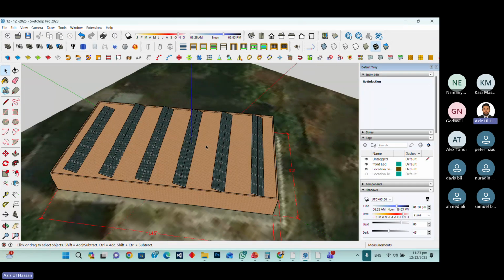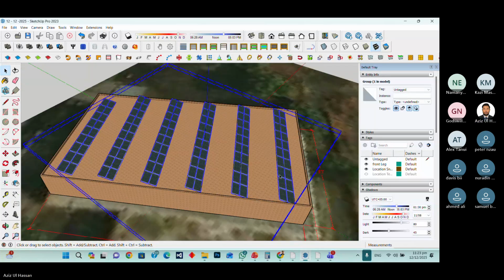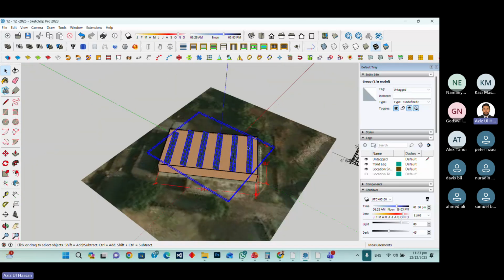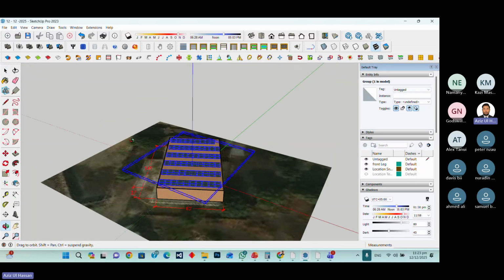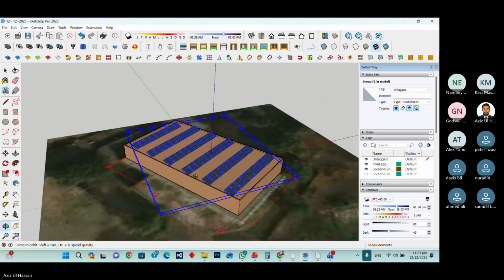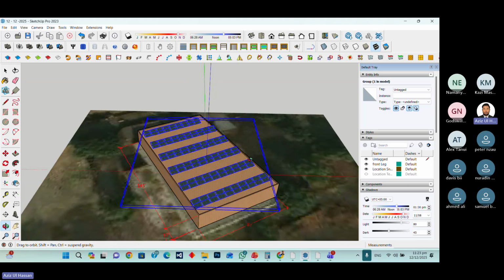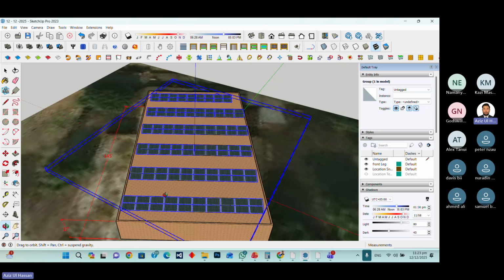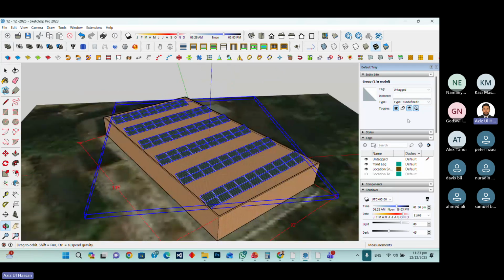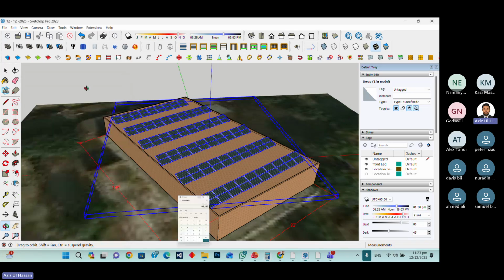The size of that building is too small, so there is less space available. We have to install 140 PV modules, but we can install only about 60 on that building, like 59 into 715 watt, which is a 42 kilowatt system.